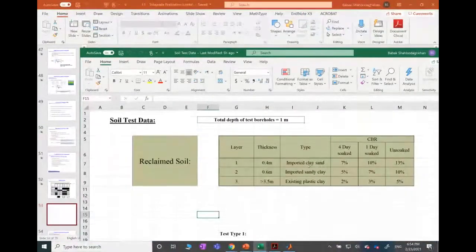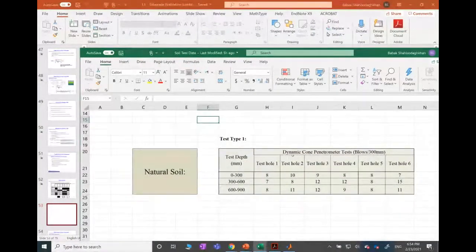These are the DCP test results. Similar to the procedure that I explained, you need to calculate the standard deviation, and you can use different software to simply calculate the value. In the assignment, DCP tests are done at numerous locations. How are we supposed to consider those while working out the design DCP? So this is very normal. You need to conduct DCP tests at different locations because the soil that we are dealing with is non-homogeneous material. So we cannot just consider one specific point.